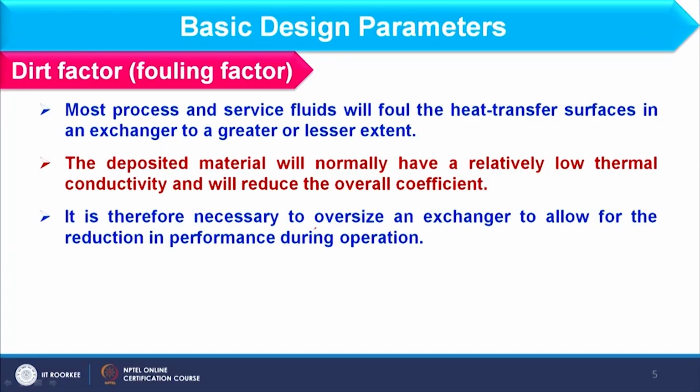So, we have to be careful while designing, because you cannot change the nature of the fluid. Whatever fluid you want to use, you have to use. You have to design in such a way that the bad tendency of the fluid can be avoided. Now, how can I do that? Let me tell you the effect of that dirt factor. Once scaling or dirt formation occurs over the tube surface or metal surface, it will offer an extra resistance, and therefore it is included in the overall heat transfer coefficient expression.